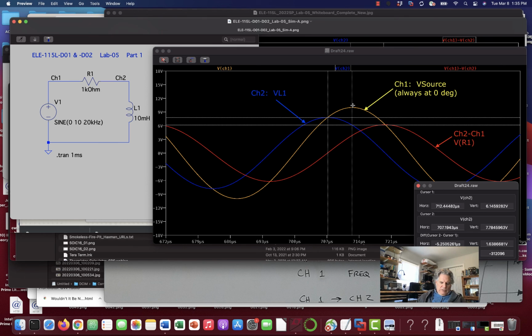And so I'm going to do something like 5.25 divided by 50 equals, and it's about 0.105. Now, what portion is that of 360 degrees? Because one whole cycle, or 50 microseconds of that waveform, is 360 degrees. So I'm going to take that and multiply it by 360 degrees, and I get 37.8 degrees. I think if you remember in lab we got about 38.